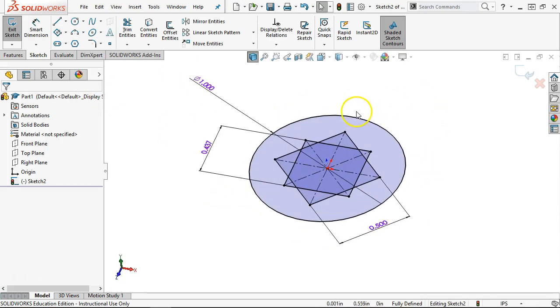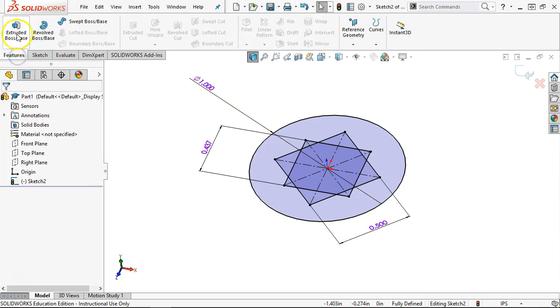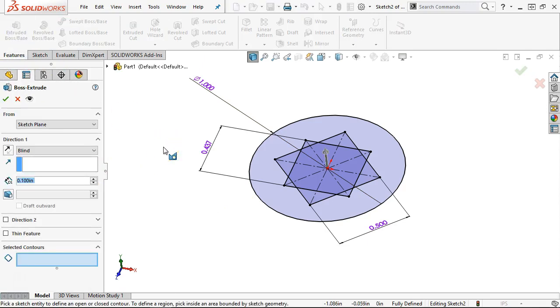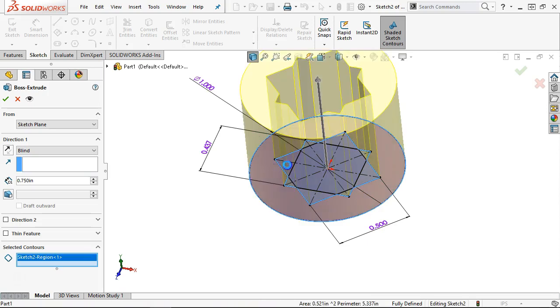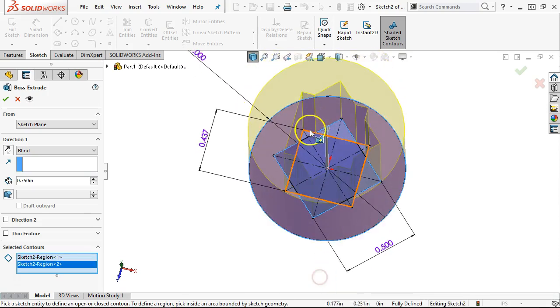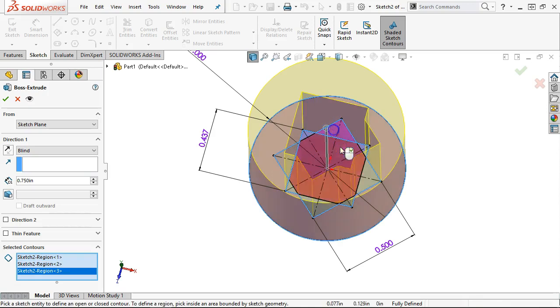And let's go ahead and make the selection. This is 3/4 of an inch in height. So extrude. The option is, do you want to trim? We can jump back over to Sketch real quick, go up to Trim Entities and start clicking and trim a bunch of items away. But I can also just go into my definition, and because I have the contours and regions, let's see, that one stays, that one goes.